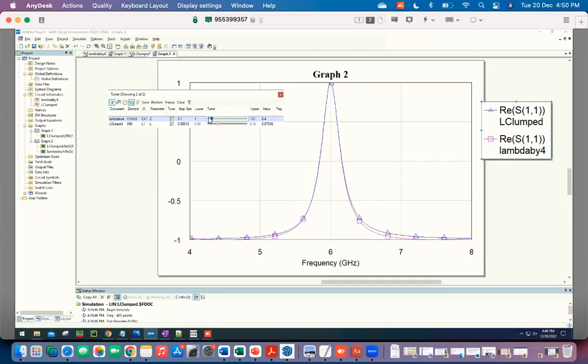So I'm at 8.4. So I am able to get more and more effective capacitance. But now the price I pay is that the transmission line is very long. And I'm no longer at the fundamental resonance, which means that I'm going to have other modes nearby. Right? So when I was at 6, the nearest mode was when it was lambda by 2 at 6 gigahertz. The next mode was at 12. So 6 gigahertz away and nothing on the lower side.